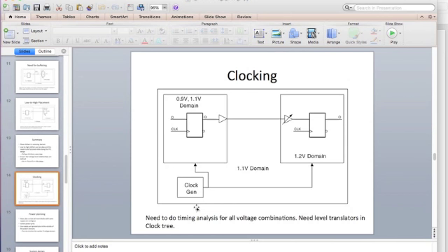It's a standard way of specifying aspects in the RTL related to power gating, where to put level shifters, etc. These are additional statements you introduce in your Verilog code, so that the tool which then synthesizes it knows what to do. You can just browse through that appendix, and you'll get some idea about that.